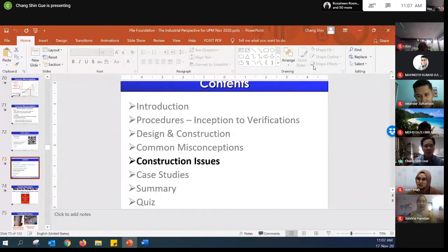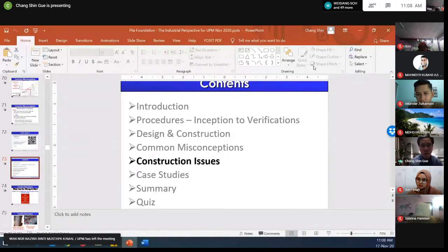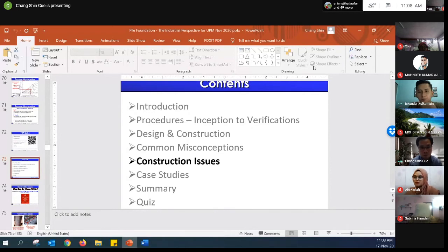Usually in practice, there is also a quantity surveyor within the project. So we will then tell them what kind of piles, and then the quantity surveyor will actually measure the amount of concrete needed and your steel. But for bored piles, for example, and if you are using driven piles, the RC piles or spun piles, then those are from the manufacturer, and they can actually give you the cost in terms of different sizes and length. Okay, I see. Thank you very much.